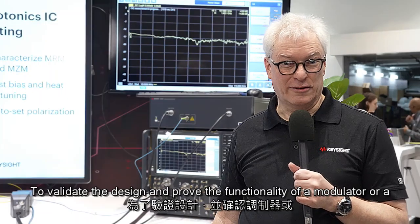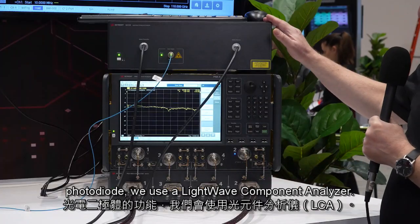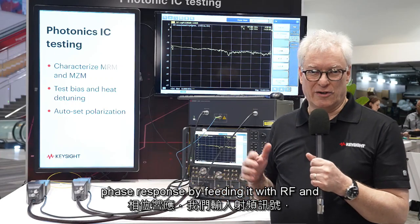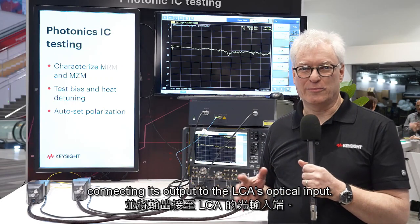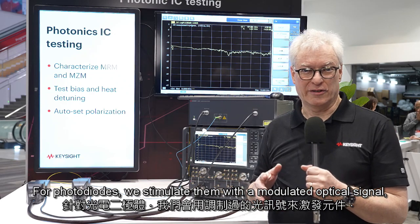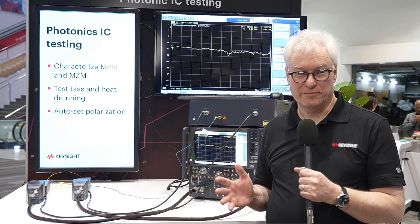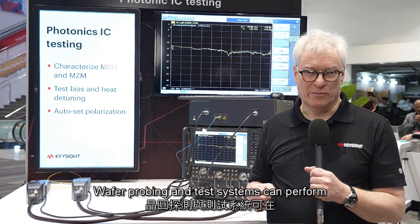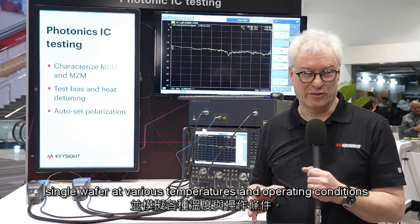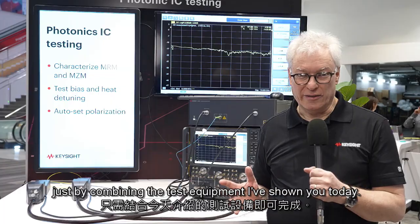To validate the design and prove the functionality of a modulator or a photodiode, we use a lightwave component analyzer. To measure the modulator's bandwidth and phase response, we feed it with RF and connect its output to the LCA's optical input. For photodiodes, we stimulate them with a modulated optical signal and measure their frequency response, adjusting bias with the source measurement unit. Wafer probing and test systems can perform thousands of measurements on a single wafer at various temperatures and operating conditions, just by combining the test equipment I've shown you today.